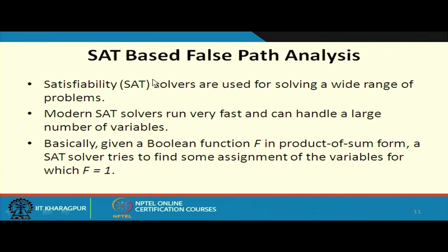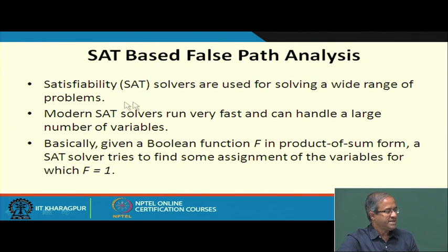So, SAT based false path analysis, what it tries to do is that, now the thing is that SAT solver is a very general kind of a tool. It can be used to solve a wide range of problems. And the SAT solvers that are available today, many of them are freely available. They run very fast and they can handle quite a large number of variables, thousands of variables they can handle.